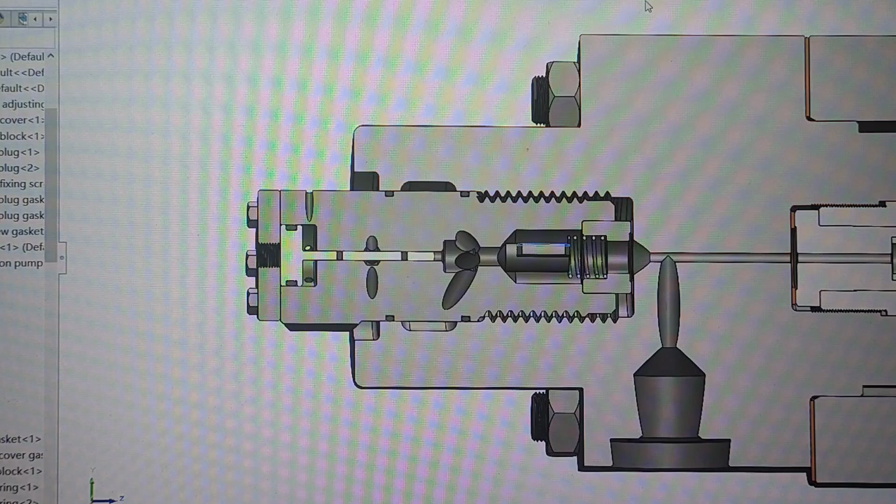Because in the air start procedure, if you supply too much fuel into the cylinder, that will lead the engine knocking or to acute pressure building. Alright. Also, the fuel is not allowed to enter into the air starting system, since the accumulated fuel will lead to the explosion of the starting air pipes. Alright, so during the air start procedure, the fuel is cut off.